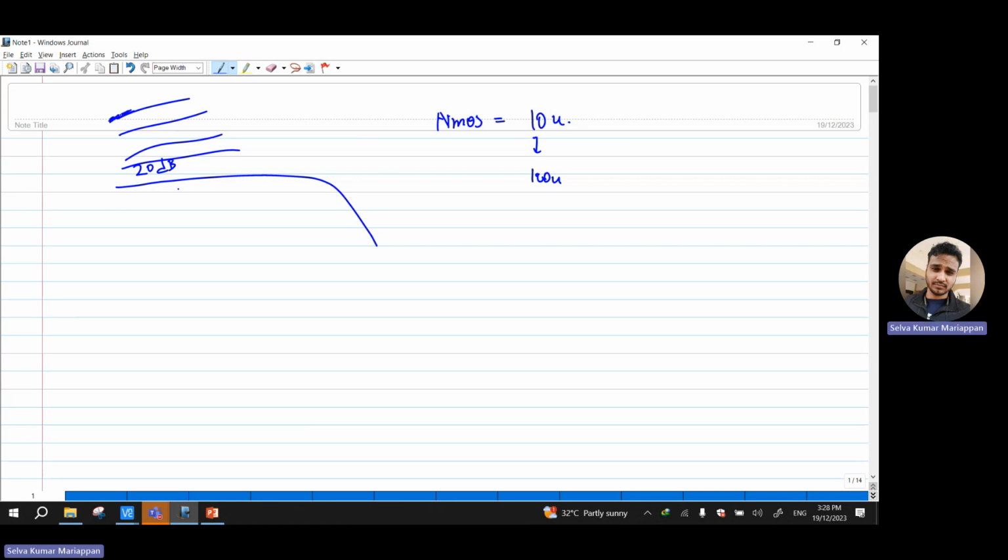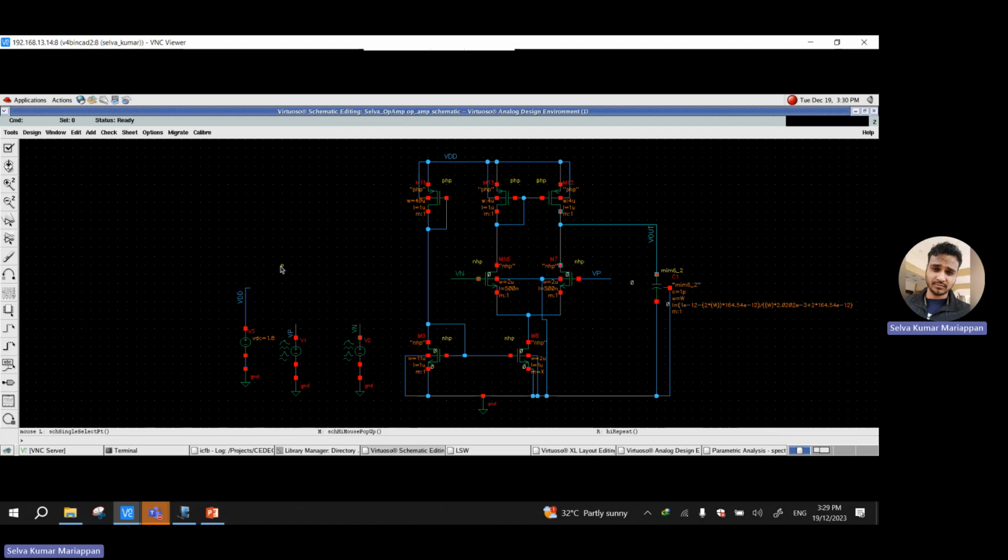Let's say the same line is here, these are different lines, and from 50 micro to 100 micro it's like no effect. So what's the value that you're going to take? Of course, you take 50 micro, okay? Because once you put 50 micro, you already achieve the maximum gain. So it's no longer needed for you to keep on increasing the size, okay? So that's how you do your parametric analysis, okay? It depends on your skills, okay? So that's on parametric analysis, okay?